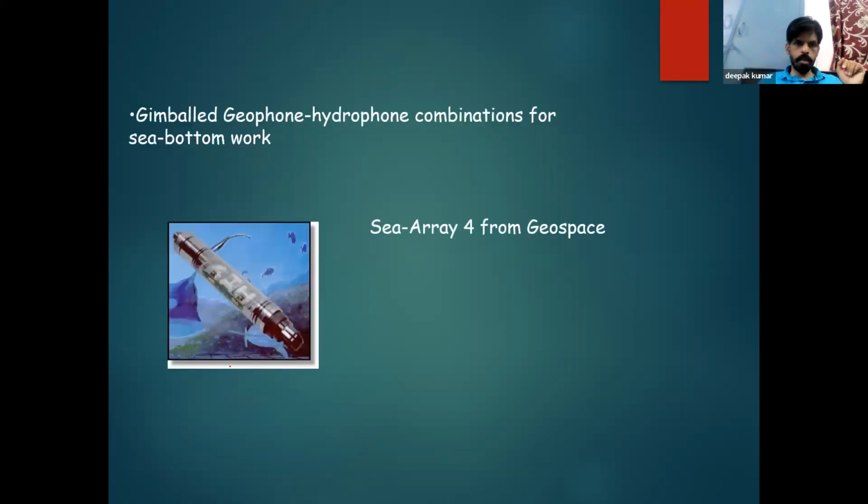This is a gimbal geophone-hydrophone, meaning it has a geophone and a hydrophone built in, but it is only used for a bottom simulating reflector survey, a BSR kind of survey. These are planted on the sea bed and connected with a continuous recording system, and are left lying on the seabed for 2, 3, 4 months. The ship will move on top of it and blast, the pressure will go down, and it will record the change in pressure, and the ground motion will also be recorded with the help of the geophone and hydrophone.